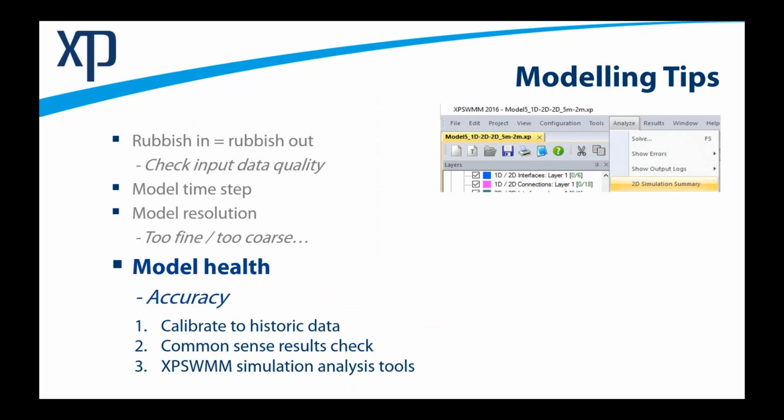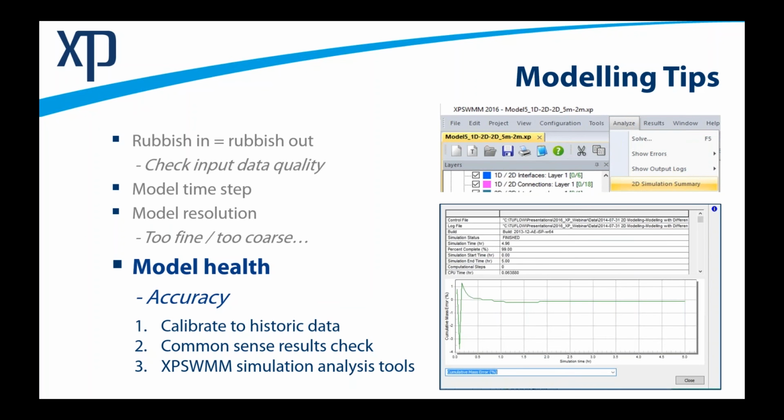What you should be aiming for is less than plus or minus 1% at the peak of your event. On warm-up, as in this case, we're seeing the mass error down around 3%, but once you're getting towards the peak of your event, where you're most interested in the results and it's not just wetting and drying, the mass error is quite good.